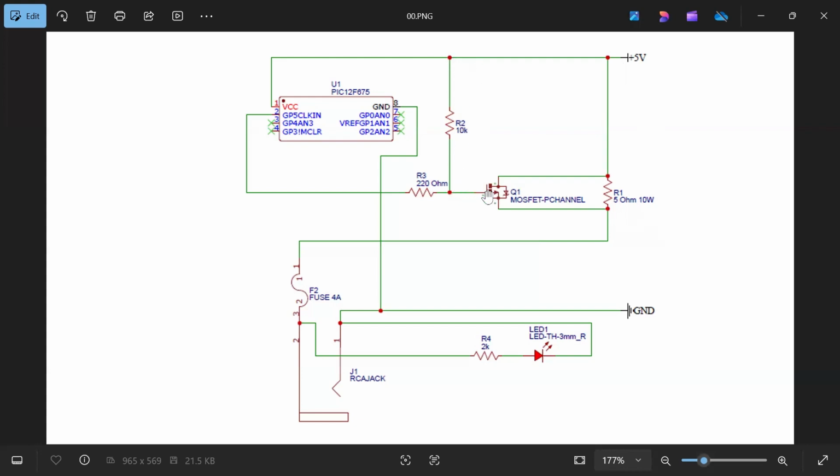That's a pull-up resistor for the MOSFET transistor. We have a current limiting resistor here for the gate of the MOSFET. And then I'm going to be using a small PIC microcontroller that's going to take care of the timing for the circuit, as to how long it's going to stay in the low power state before it switches to the high power state.